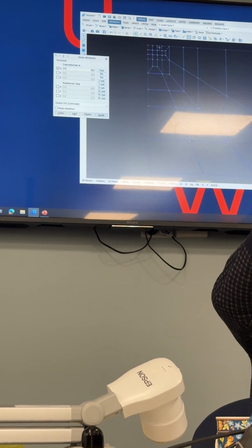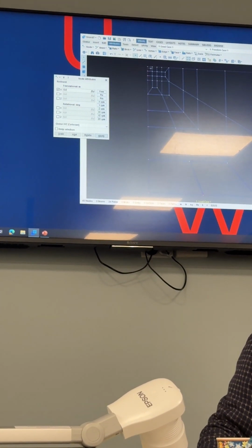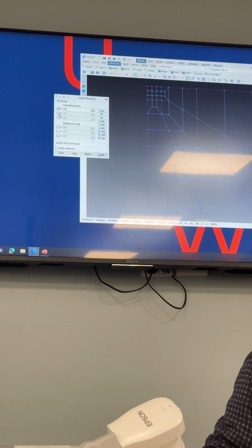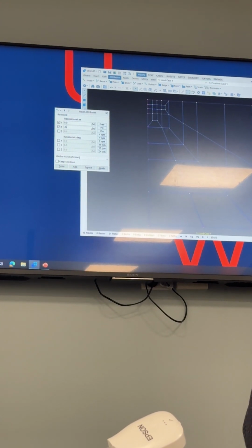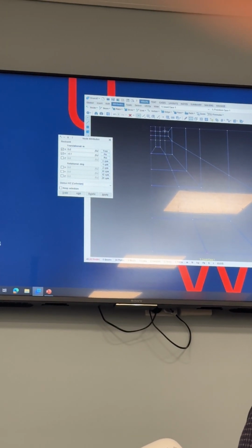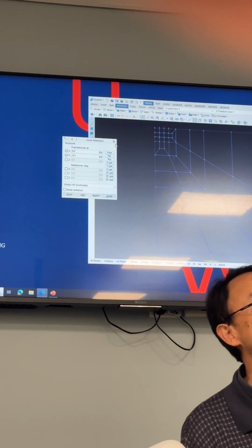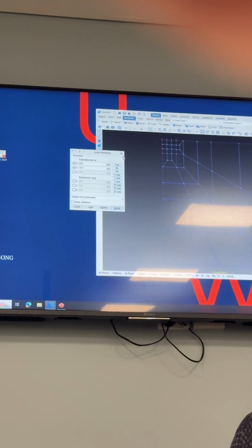So the displacement of the footing is the displacement for these 3 elements. So it is x direction 0, y direction minus 0.1. Apply. Okay, with this done, you have imported the boundary condition.